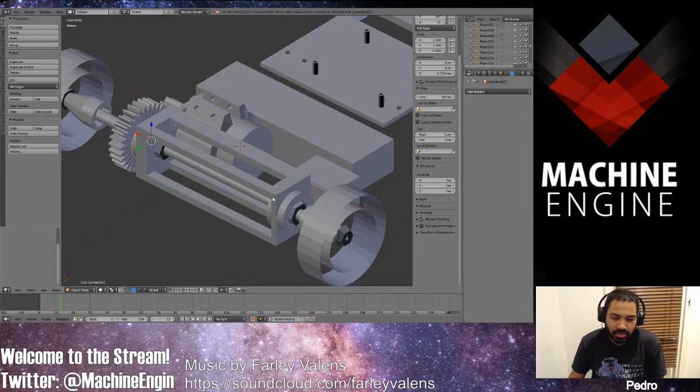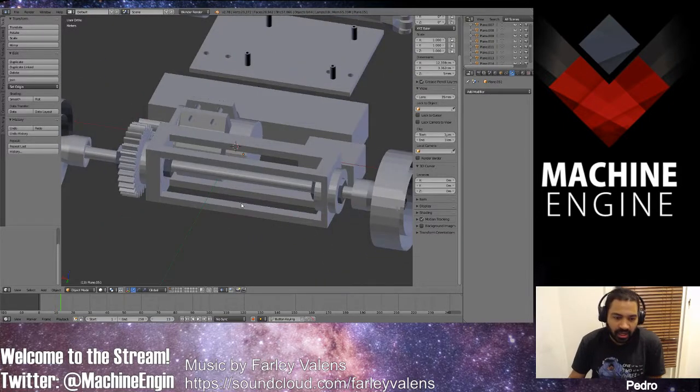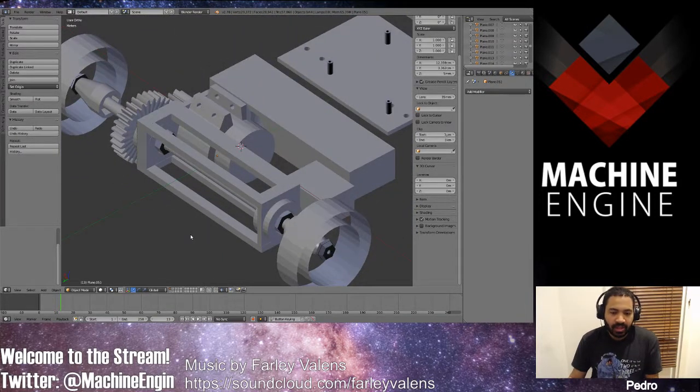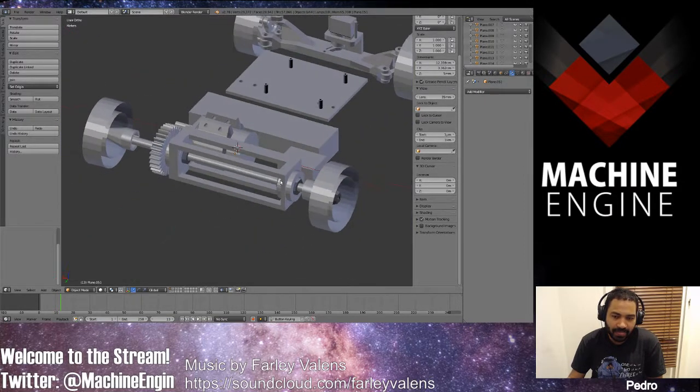What I could do is break it in pieces here and put screws here, so I can keep these guys one length, but then just screw them together there at the ends. That's also a possibility. That'll probably work better than breaking it in the middle. Just make screw holes here, 4 of them, and screw it in from the sides. That'll probably work pretty well. But I want to try printing it out as 1 piece to keep it really stiff. If it doesn't work, I'll add the screws at the corners.